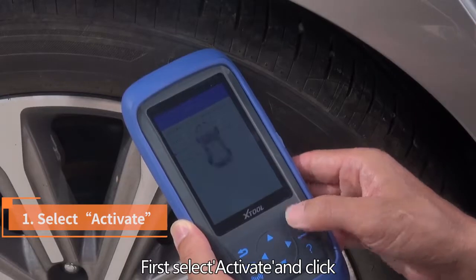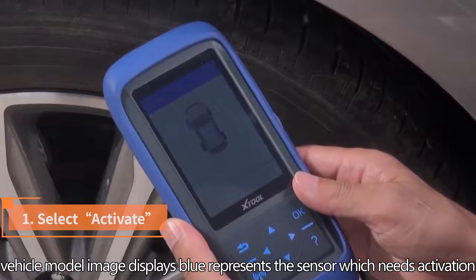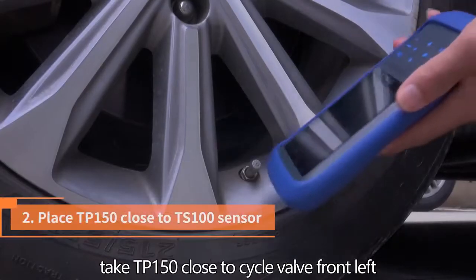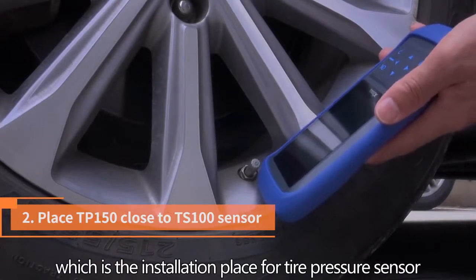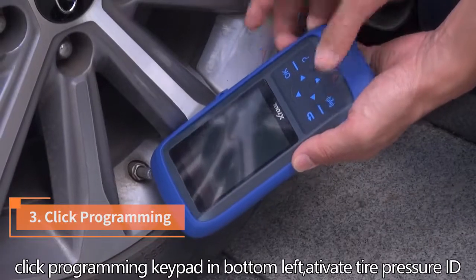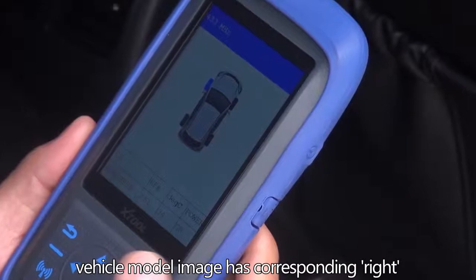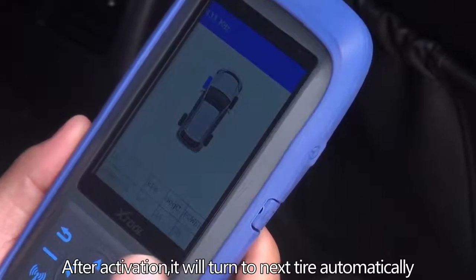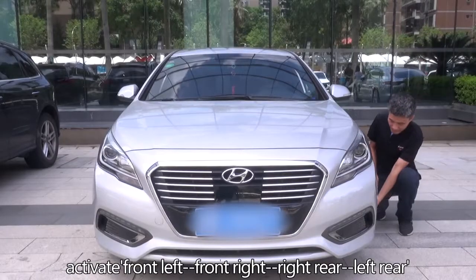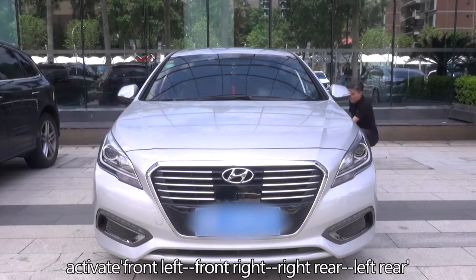First, select Activate and click. Vehicle model image displays blue represents the sensor which needs activation. Take TP150 close to the valve on the front left, which is the installation place for tire pressure sensor. Click Programming keypad in bottom left, activate tire pressure ID. Vehicle model image has corresponding response. After activation, it will turn to the next tire automatically. Activate front left, front right, right rear, left rear.